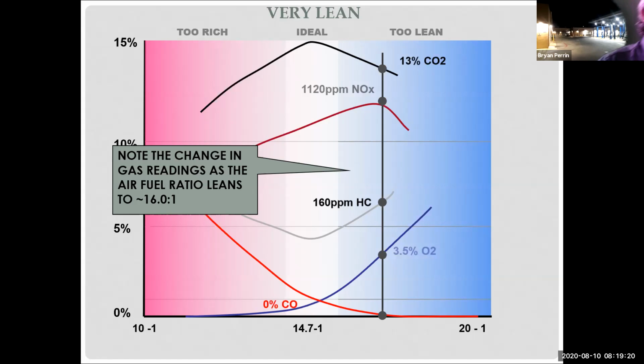No, it doesn't melt down because the 2500 is at the flame kernel. It's not throughout the combustion chamber. So the valves are not 2500 degrees, but combustion chamber temperatures are hitting 2500 degrees. And it only does that for a very, very short period of time. It's not a sustained temperature, which, you're right, would cause things to melt down. It's only happening for a split second.